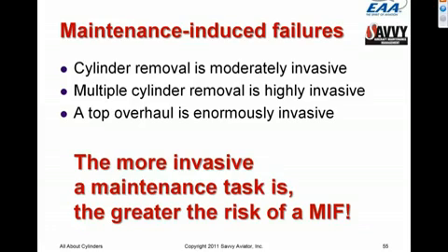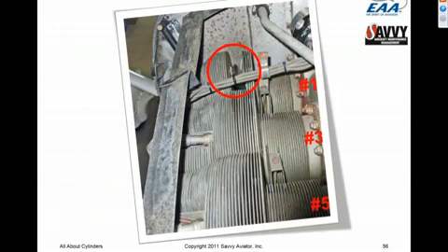It's a very controversial opinion. A lot of mechanics get mad at me when I say stuff like that. But like I said, I've just seen too many of these airplanes fall out of the sky because a mechanic did something wrong during the cylinder removal or reinstallation. This is a 182 that was flying over the Badlands of Montana. It had a catastrophic cylinder head separation.